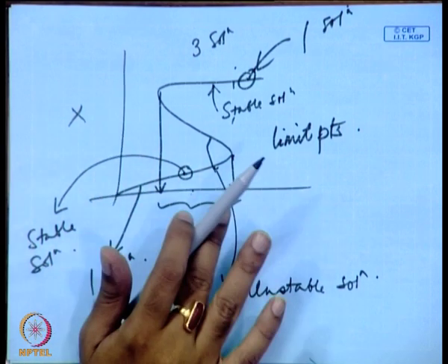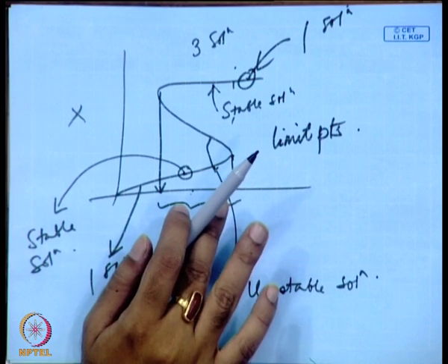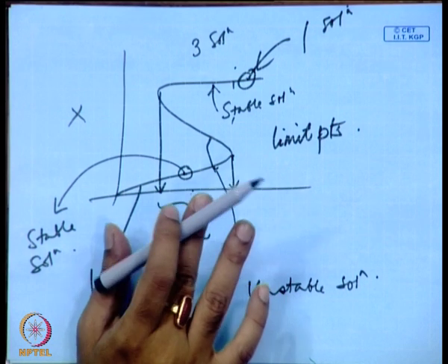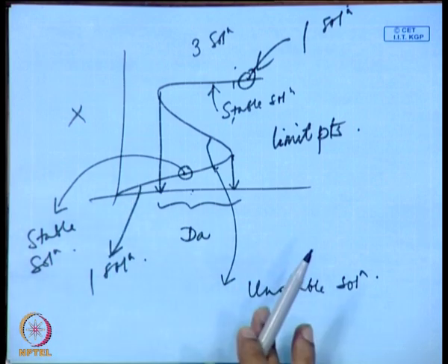So, your aim is never to operate close to the unstable branch, and how do you ensure that? If as an engineer, for example, you are to operate your plant or your reactor in a certain parameter range, say residence time or liquid volume or the substrate concentration, whatever it is, how will you ensure that it does not go to the unstable branch?